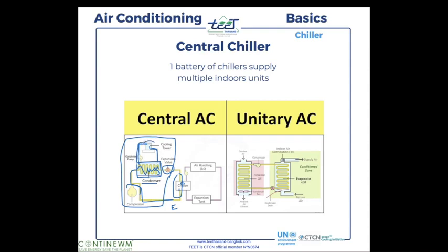We cool that water with a system called the cooling tower, which is on the roof. Then the refrigerant fluid is cooled and gets back to the chiller to cool the water in the chiller.